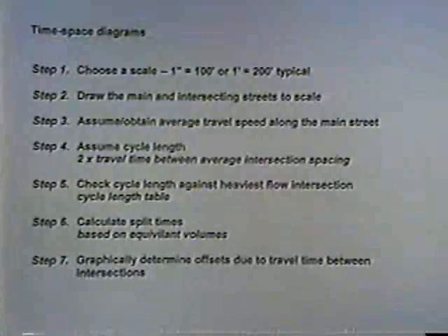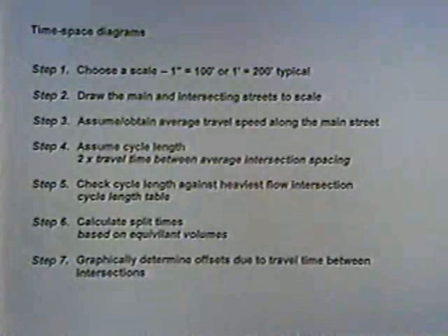We talk about traffic signals. One of the concepts they introduced in your reference manual is time-space diagrams. There's a time-space diagram in your notes on page 1633, in your reference manual on 1633, and the next page of your notes. Essentially, you're looking at a scale. Typical values are 1 inch equals 100 feet or 1 inch equals 200 feet. You draw your main and intersecting streets to scale.